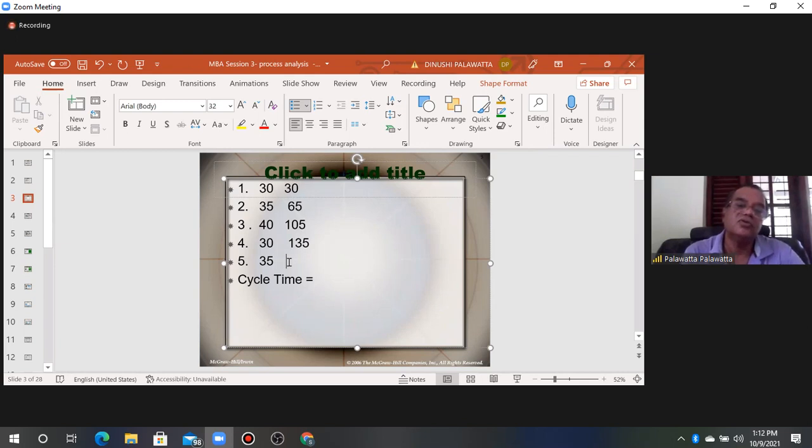Finally, 240. So then you see time to produce the first one is 30 seconds. And from first one to second one is 35 seconds. From second one to third one is 40 seconds. So like that. And then cycle time is the average time.